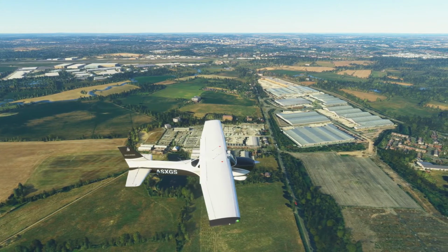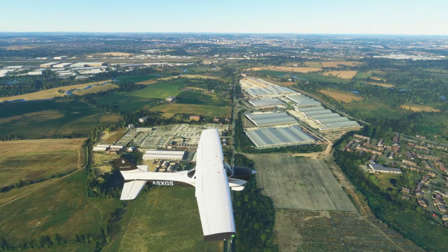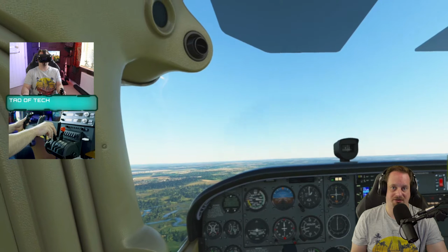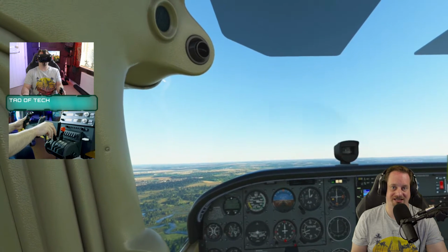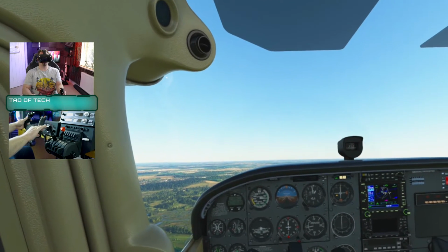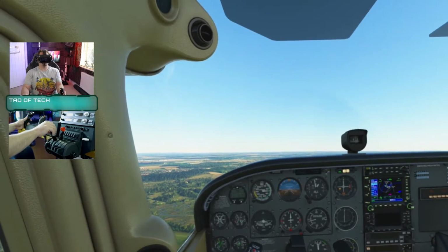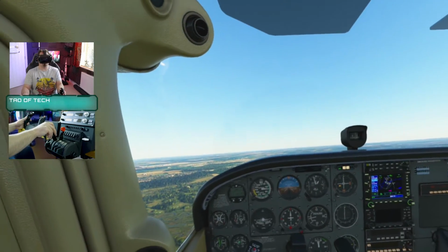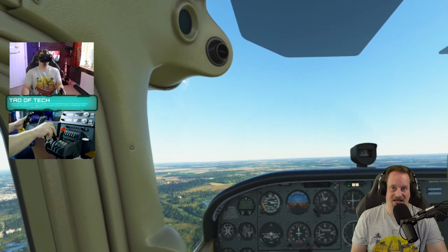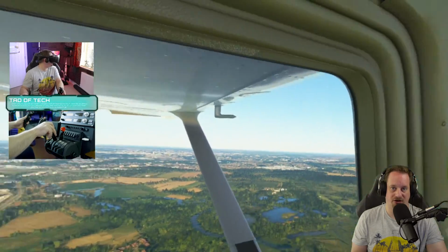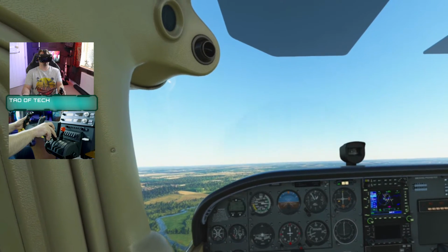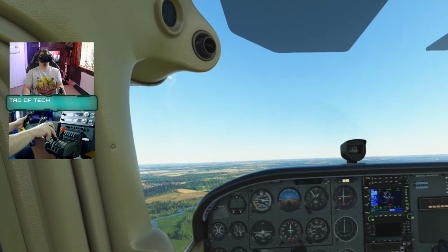There's our first notch of flaps going in. We're abeam with the airfield. Reducing the power to 1700 RPM, starting a descent of 200 to 300 feet per minute. We will want to make our turn onto base, again when the airfield is 45 degrees behind us. So quick glances behind us to see when that is.